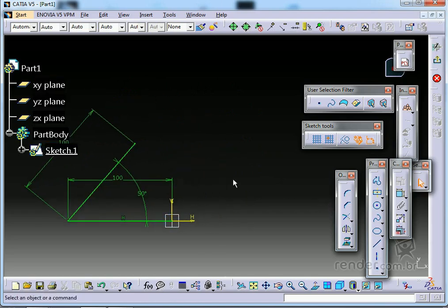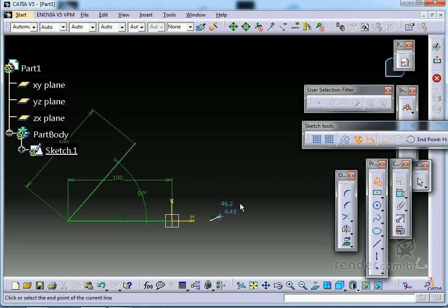If I want a continuous line, if I want to make a square, I have to take the profile command, then I click, go up, turn, always turning a straight line to be blue, go down until it is dashed, meaning that it found it. I click and it closed here.